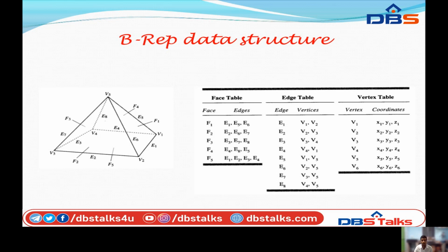The edge table consists of edges and vertices. Coming to edge E1, it consists of vertices V1 and V2. Edge E1 is generated using vertices V1 and V2. Similarly, E2, E3, E4, E5, E6, E7, E8. Coming to the vertex table, V1 is the vertex. Here I am showing the vertex. A vertex is generated using coordinate points on the X, Y, Z axes: X1, Y1, Z1. For vertex V2, X2, Y2, Z2. This is the procedure for the boundary representation data structure.